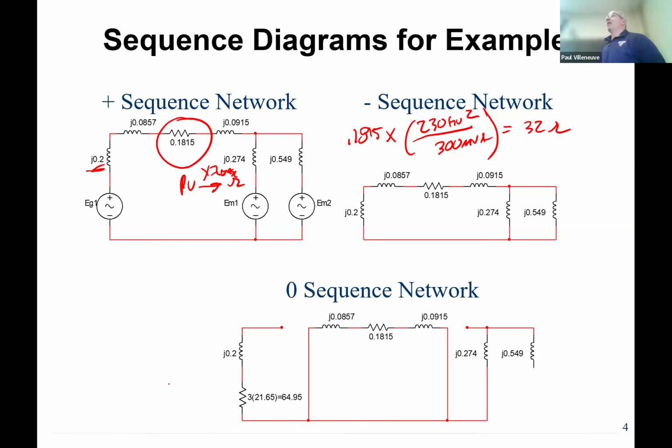All right, I'm giving you a new job. You're the plant engineer for a new power facility, and you need to go out and purchase a 13.8 kV generator. And you tell the manufacturer, build me a 13.8 kV generator with a voltage source in the positive sequence network and a voltage source in the negative sequence network. What did you do by telling them that?